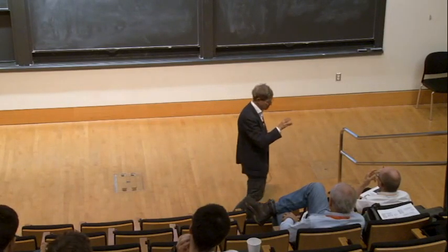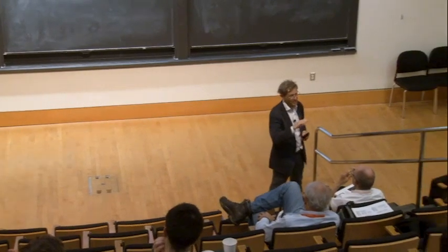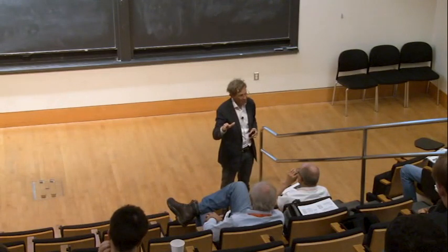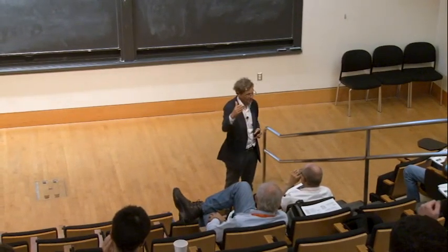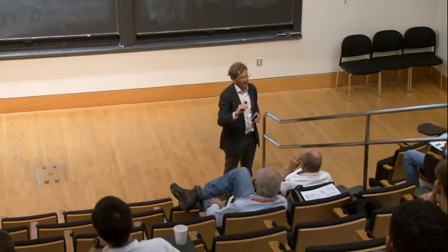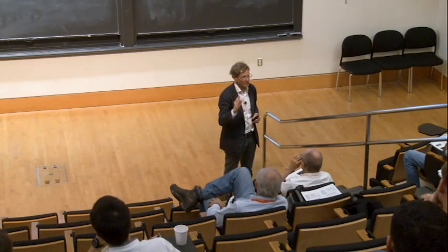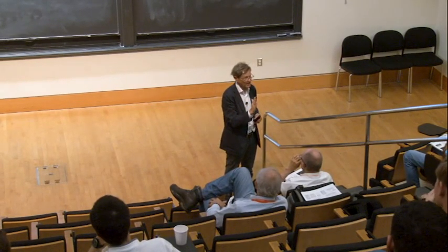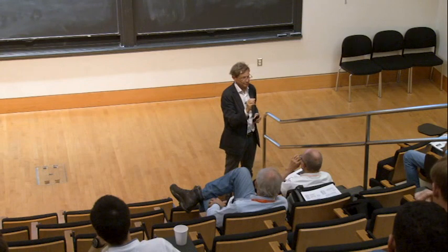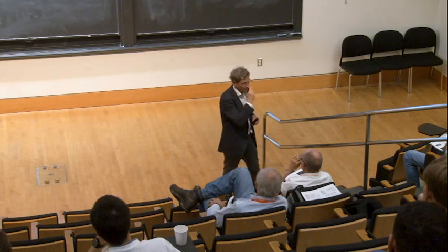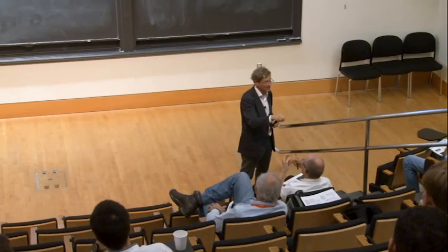that's a big question not yet fully answered. Why do we get standing modes? Why do we get spinning modes? We have some answers. One reason for getting standing modes is to have a slight asymmetry. For example, you put the spark plug and you leave it there.